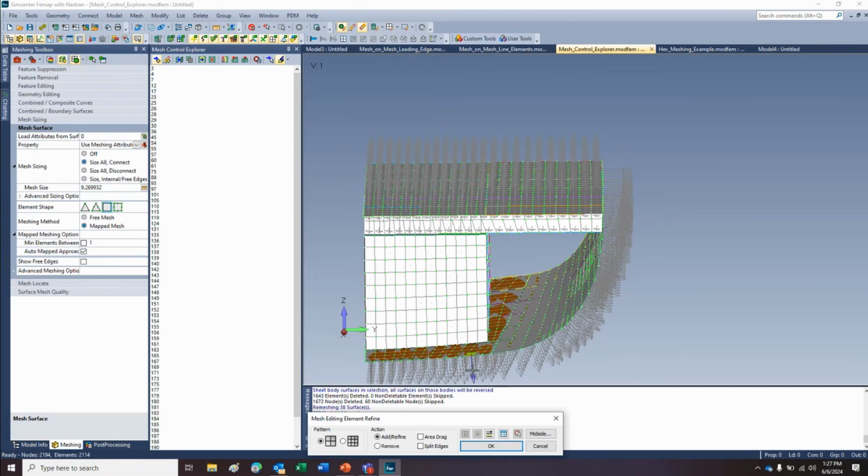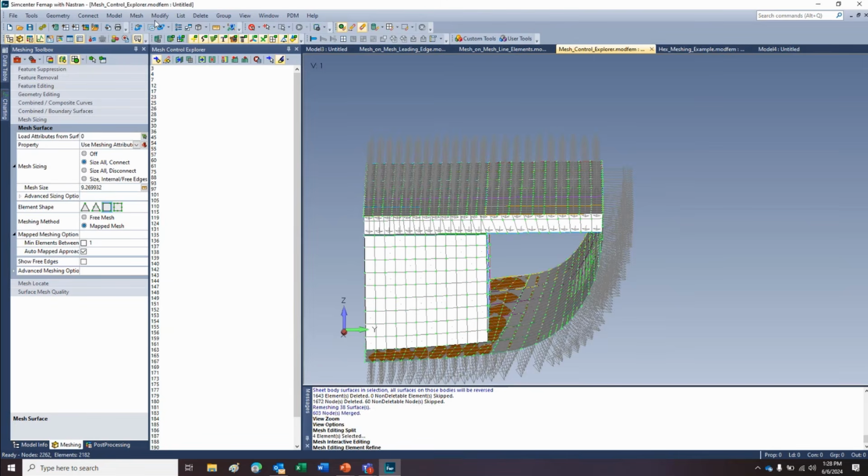Okay. But if you did have a mismatched mesh, we do have the ability to create an R-spline in Femap. It's rather manual, but if they're in your model, we will read them in, and then you can reuse them, and we'll spit them back out. And that's part of the reason we did the R bar and the R rod, because it was in so many models.